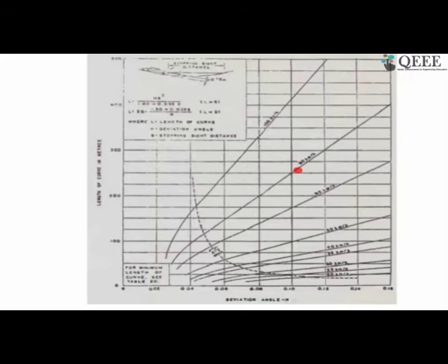Another thing is that if you are going into the valley curve, naturally because of the downhill or descending gradient, your speed is going to keep on increasing. If you don't check it, that is where the vehicle can get into an accident. So this becomes more critical than the summit curve, because in the summit curve, the vehicle is going on an ascending gradient, so the speed is naturally checked, and unless someone is pushing the accelerator too much, they are not going to overspeed easily. Here in the valley curve, even without pressing the accelerator, the vehicle can.